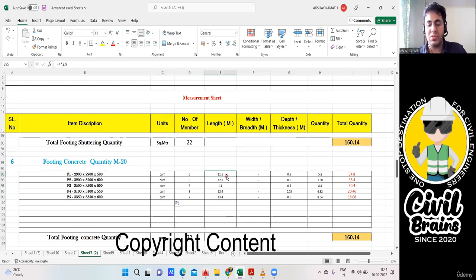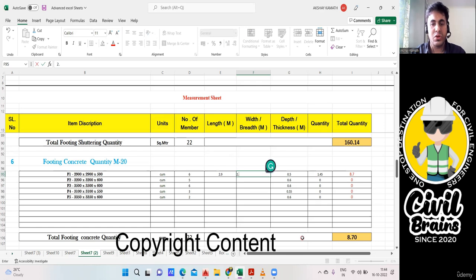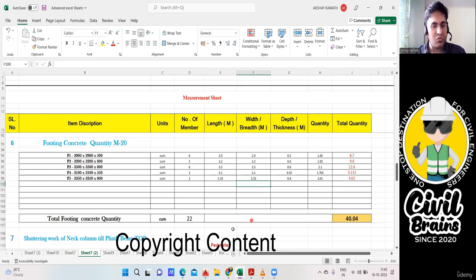So how will it happen now? Very simple. Delete all these things. This also you delete. And then you just have to write 2.9. That side also it is 2.9. We are doing the concrete quantity, no? Footing, 2.9, 2.9 and the depth of your footing. Done. 3.2 and this is 3.2. 3.5, 3.5. 3.1. So this is a bit easy for us, because all the footings are of the same size, the length and the breadth. So there are not many difficulties. Done. The concrete quantity is ready. You require 40.04 cubic meter of concrete for these 22 footings.